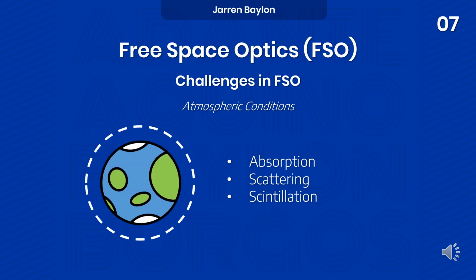Next, we have the atmospheric conditions. So first is the absorption. Absorption occurs when suspended water molecules in the terrestrial atmosphere extinguish photons. This causes a decrease in the power density of the FSO beam and directly affects the availability of telecom services. However, the typical wavelength values of FSO systems are 785, 850, and 1500 nanometers. Now, these wavelengths correspond to atmospheric windows where the attenuation is very small. Thus, the absorption attenuation is also very small.